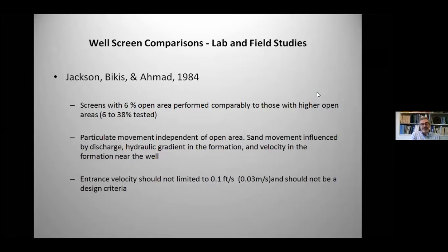And again, many of us subscribe to this thought process today. As those of us who are hydrogeologists on the staff, we like to think, at least I'd like to think, this is geologically controlled. Our entrance velocity is a result of the hydrodynamic properties of the aquifer, combined with the stresses applied by the pump. A given screen cannot determine what the entrance velocity is by itself. You need to complete the structure, conclude with the pump tests, and then determine what the incremental velocities are over the overall screened intervals, not just an average.